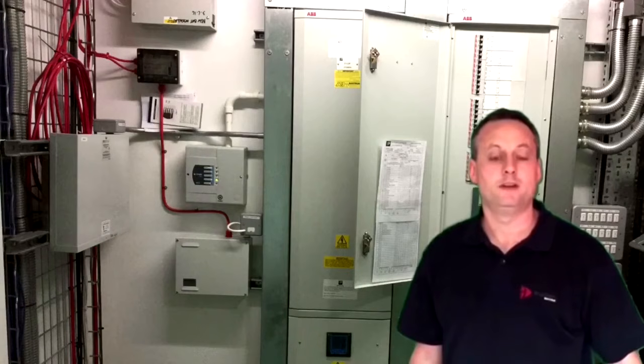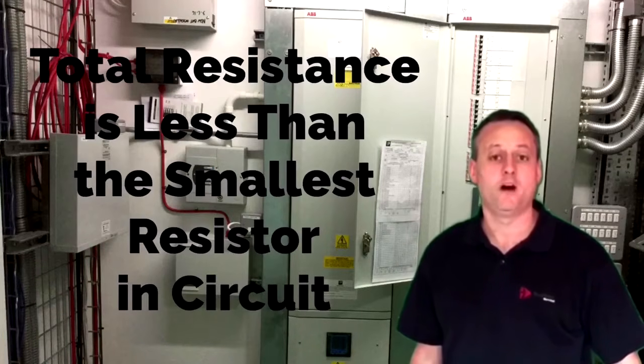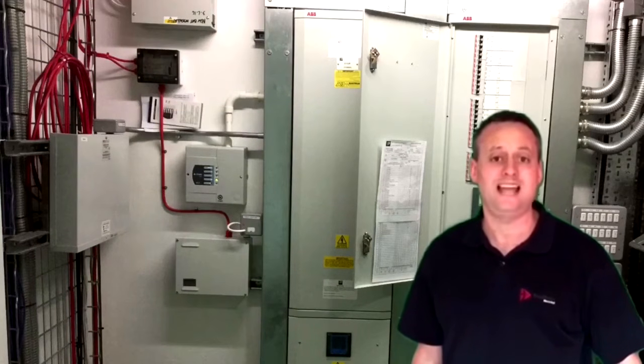Another one worth remembering on parallel resistors is if we have a 200 ohm resistor, a 200 ohm resistor, and a 1 ohm resistor connected in parallel, the total resistance in the circuit is less than 1 ohm. We are heading towards a multi-choice exam that may give you answers with only one resistor value less than the smallest one of those connected in parallel.